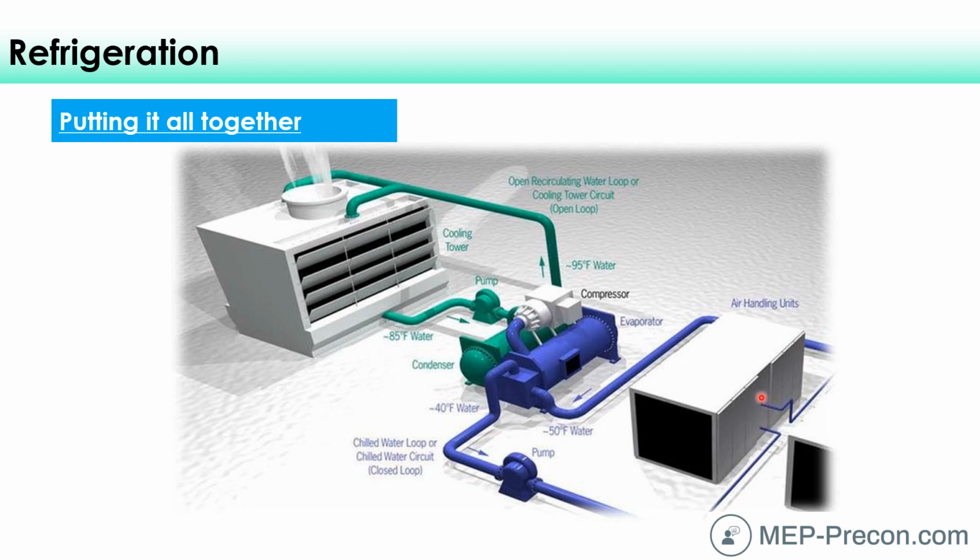And then as it does so, we want to cool it off. We want to accommodate that with cold air. And so we're going to pull that air from that room through that, and it's going to give up those BTUs that are in that air into this coil. It's going to jump from the air into that coil because it sees that's 40-degree water. Great, I love that. And so the air that comes out of here now, this supply air from this air handling unit, is nice and cold. We push it down into the space and it mixes with the warm air, and some of that warm air comes back here, and we continue that cycle. And that's how we cool the air.